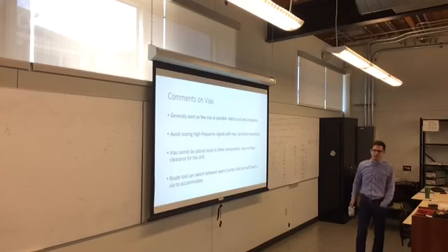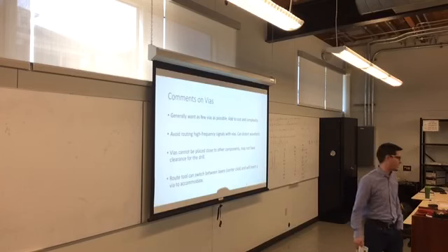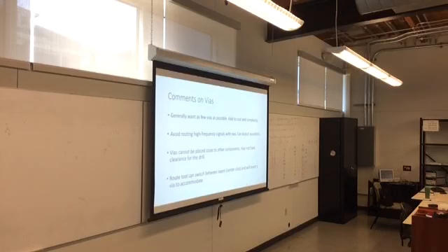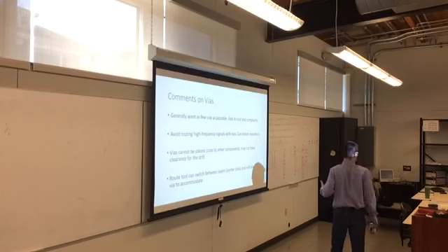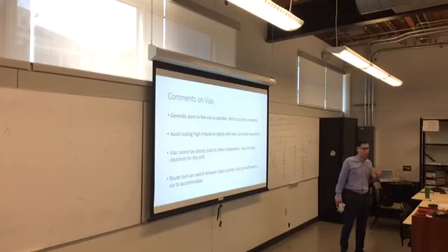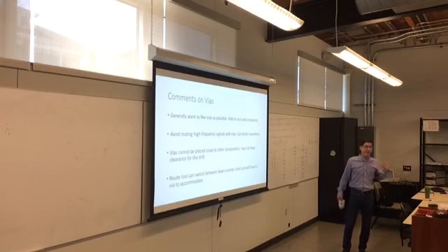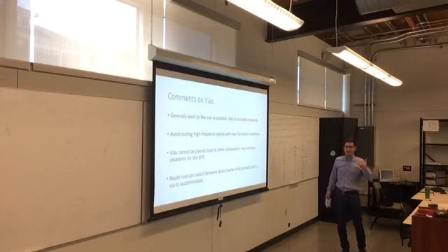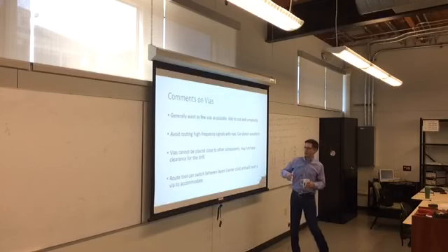So, a couple comments on vias. You generally want as few as possible. That means there are fewer holes in the board and it's a less complicated routing. For a high-speed signal, and high speed is sort of whatever you want to make it, megahertz, gigahertz, having the signal go down a hole and out screws with its ability, so it can distort the waveforms of high-frequency signals. So I would generally avoid vias for anything over a couple megahertz. Actually, I wouldn't put any high-frequency signal on a via because it's going to induce some resistance and mess with the signal.